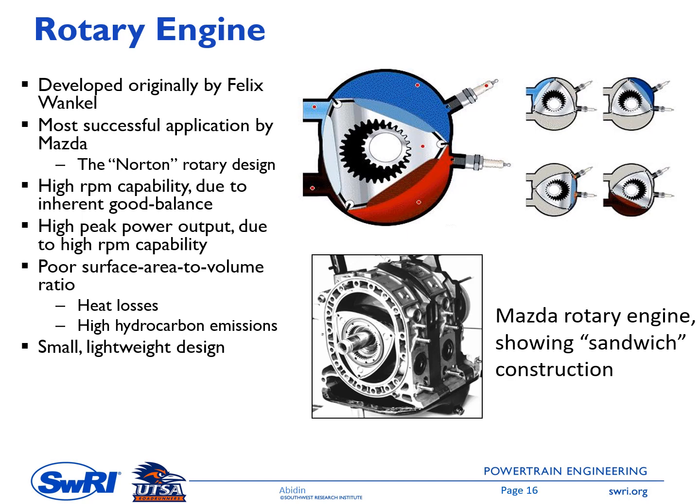A good thing for this engine type is its compactness. It can operate at a very high engine speed with very good balance, because it doesn't have a reciprocating movement. It's just a rotating part, sometimes called a rotor. It also has a high peak power output due to high RPM. Once again, the power is a function of the torque times engine speed. So if you increase N, you will also have higher power, P here.